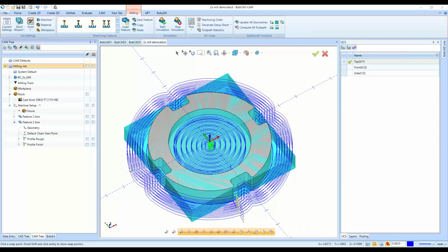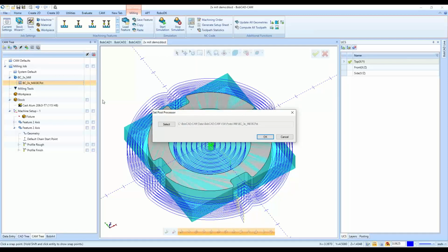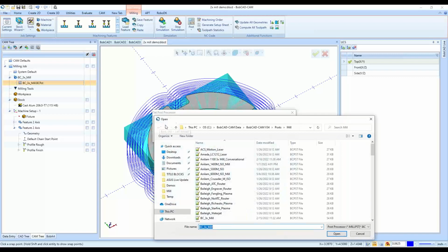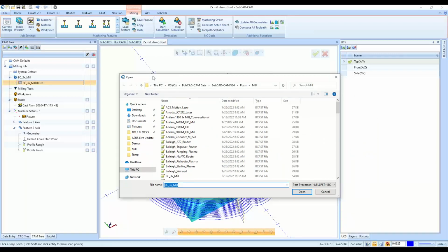Now that everything's cut to size, we can review everything, make sure the feed rates are what we want, plunge, feed rate, and all of those operations. Once everything is done, we select a certain post-processor. So the next step is our post-processor, it's this icon of a controller. We right-click and edit. We can select our post-processor. So the post-processor is a file that will format the G-code specifically to your controller type.